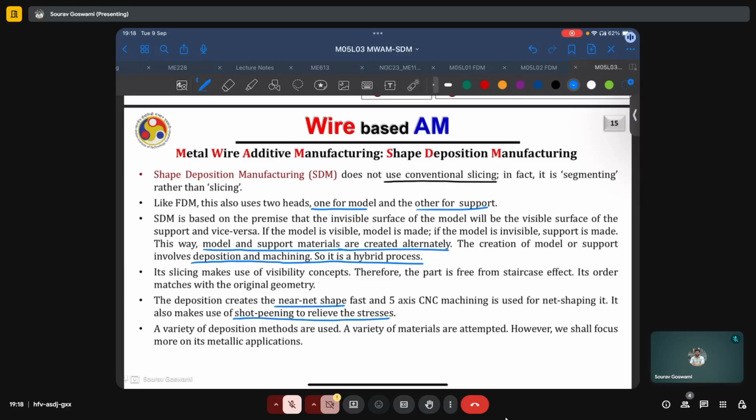We know that shot peening is a technique which is used either for stress relieving or in some cases also to introduce compressive residual stresses into a part. Parts manufactured via a fusion process, which will undergo a phase change, that is, its solid material will be melted and then solidified again, typically will have some tensile stresses.